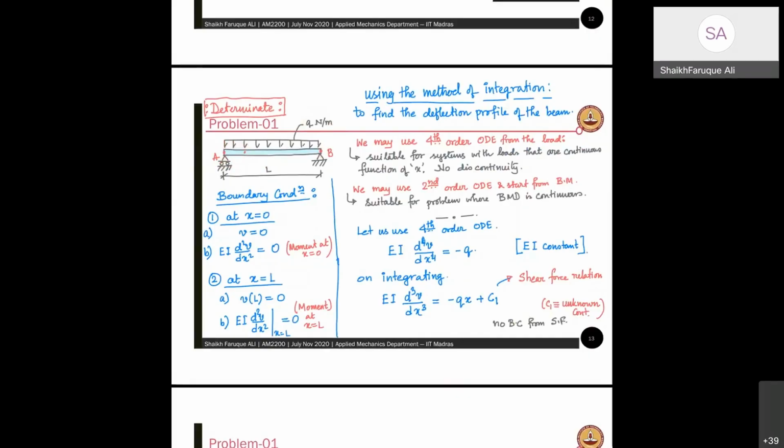Right, and there is this length here. Okay, so what you are doing is you have a load, and you are dividing the load into a line load. Line load in the sense that you have a load that is distributed over the area, right? When you call it pressure, it is distributed over the area. Then you calculate it so that you get a line load. When you say a line load, it is distributed over the line, right? So it's going to be Newton per meter.